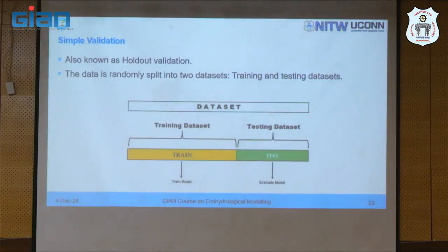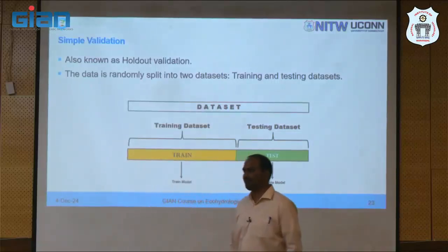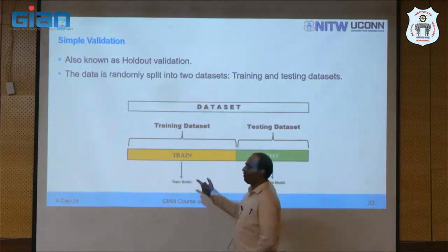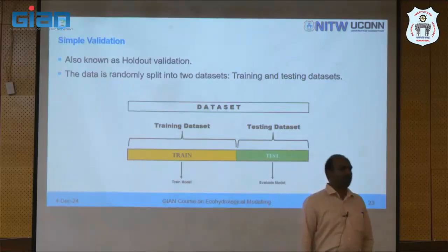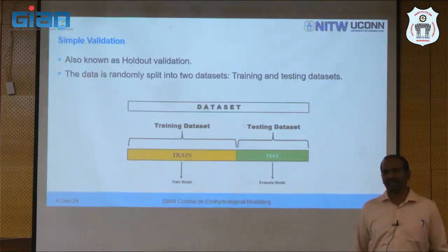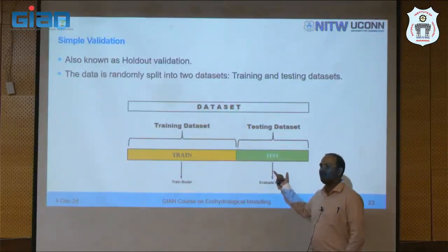When you do that, it makes sure that the model is trained or calibrated by considering all the possible scenarios that a catchment may have. Now let's say you have a 10-year data set, and you have taken the first 6 years for calibration, next 4 years for validation. Now let's assume that out of your first 6 years, 5 years you have received above normal rainfall. That means it's wet years. Now in your validation period, all 4 years were dry periods.